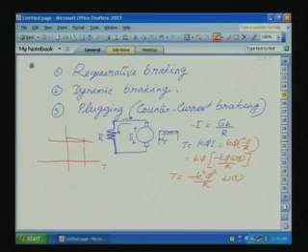So from A to B, speed is the same, speed cannot change instantaneously. A to B, if you see this point, the armature current will come to 0 from this side to this side, and quickly, because R is connected, current will go to a negative maximum torque decided by our R.